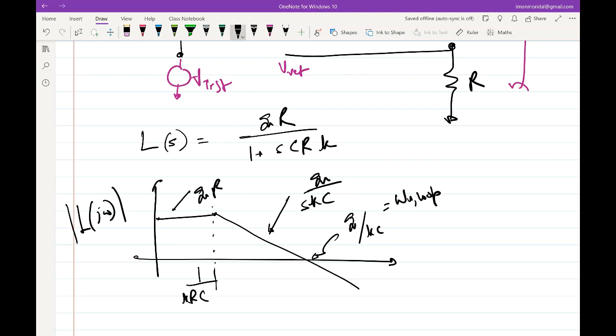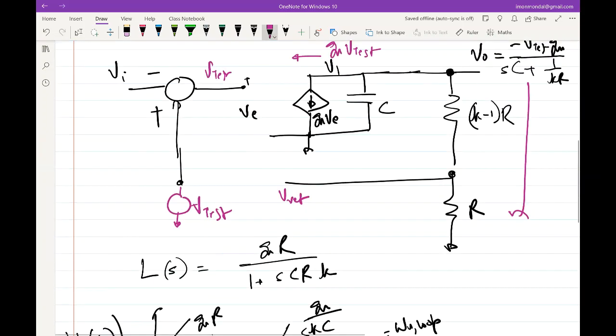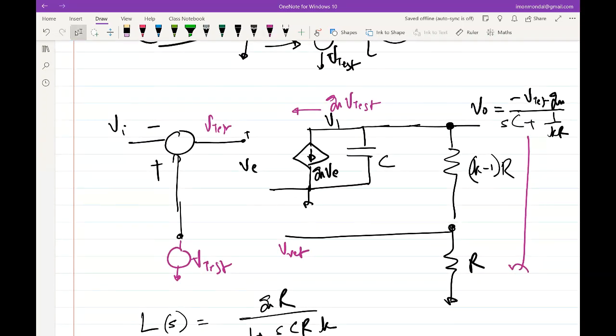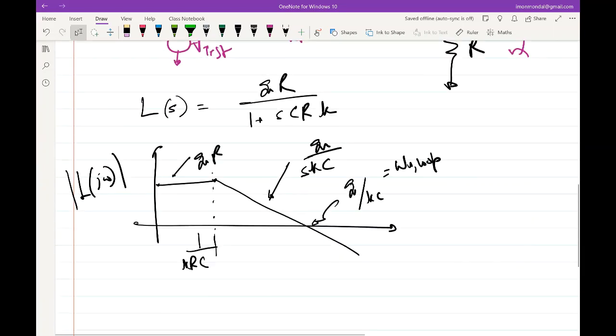So with respect to an ideal integrator, what has changed and what has not changed? In other words, when I say ideal integrator, I mean that this VCCS with capacitance was buffered with a voltage controlled voltage source, right? So what has changed? DC gain clearly has changed. What has not changed?